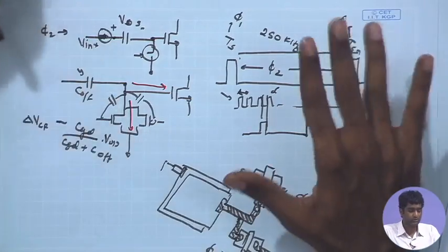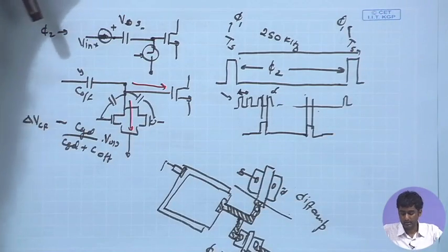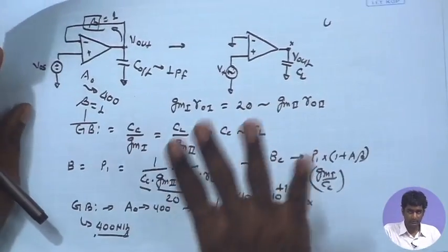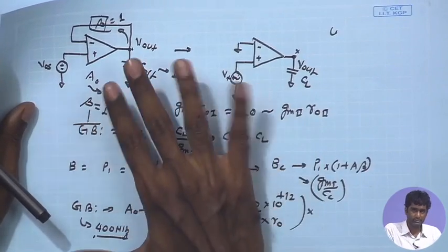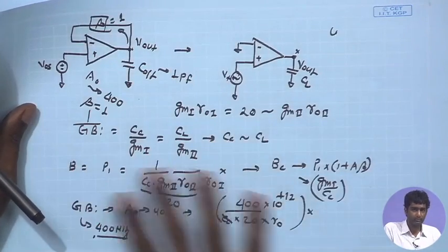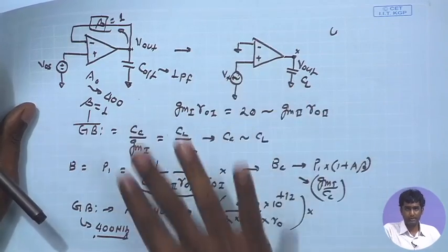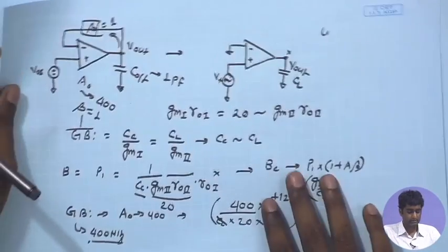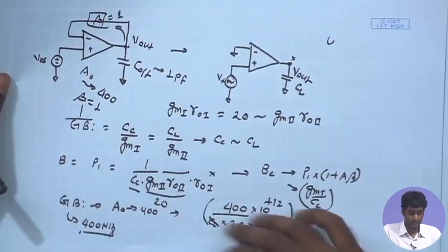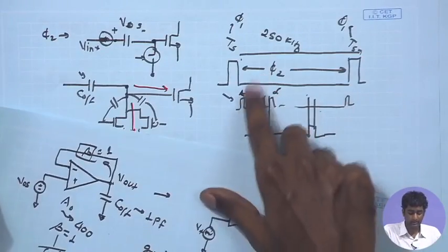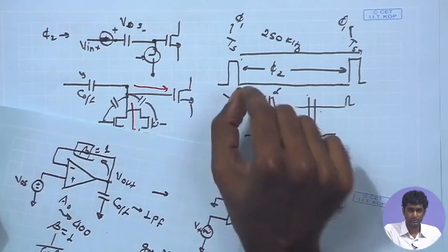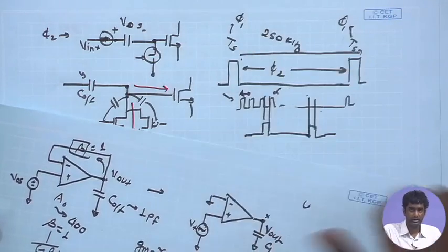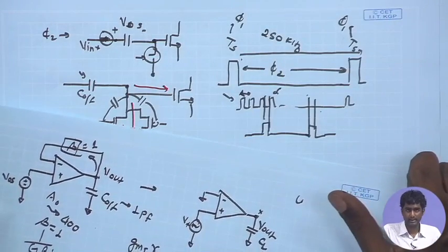But for the time being, let us focus on the closed loop operation, and we have just seen that for the 7-bit precision and the specs that we started with for our comparator, we are in a safe position. The closed loop bandwidth is very much within a single clock, or is in fact significantly higher than the clock frequency that we are using in the system. So, just a single clock pulse is good enough for our offset sampling.